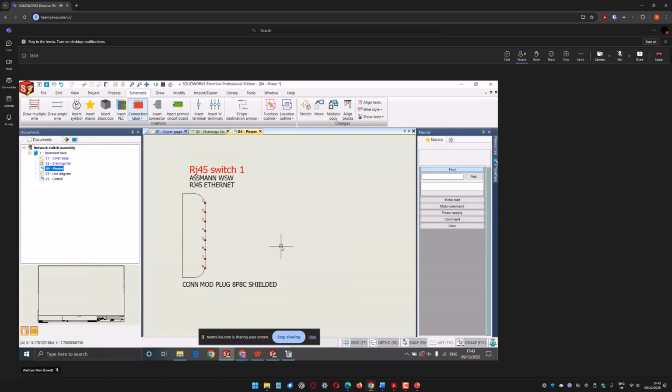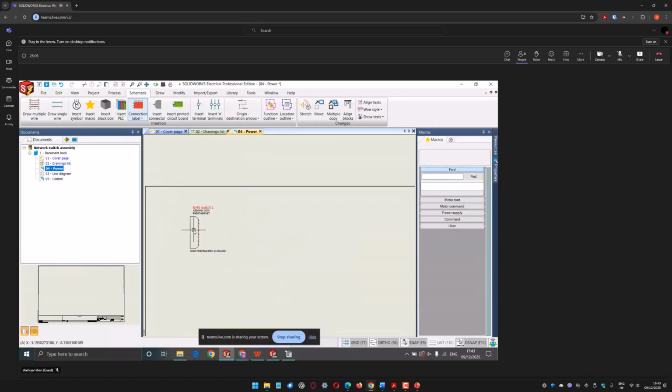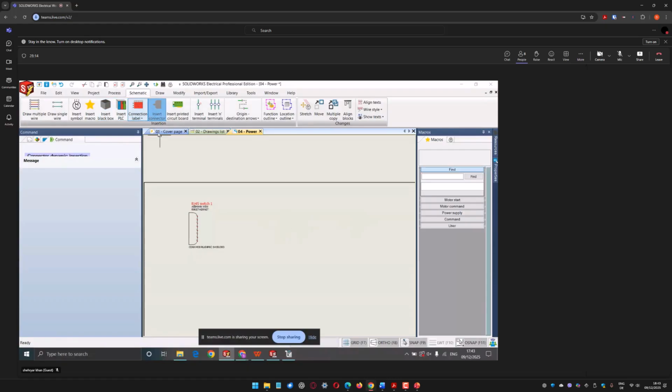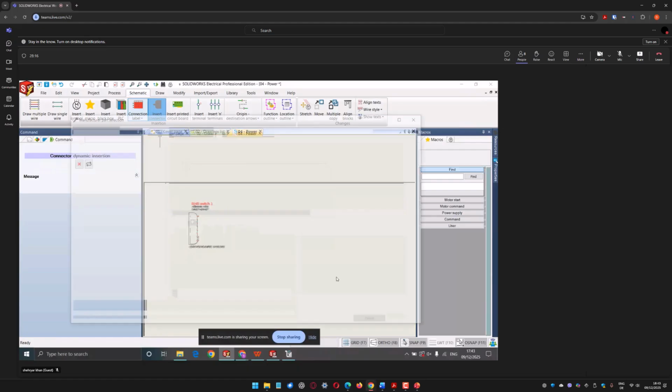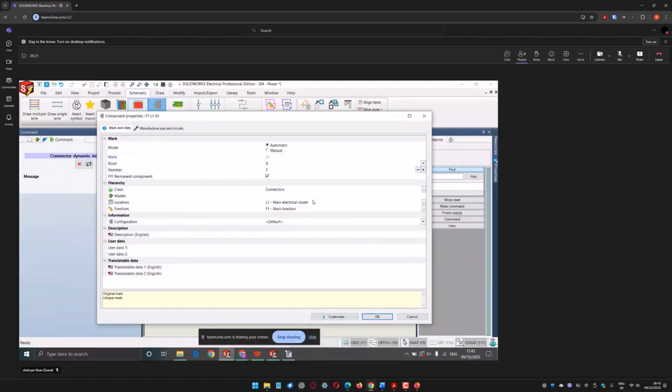And from here on, we need another connector which is going into this, and we can take it to another component. So what I'll do, I'll create a new connector, and then search again. The same type of connector is here, so I'll just put that and define its properties. RJ45 ETH. Okay, this time it's 1 gig, 1 gig switch.